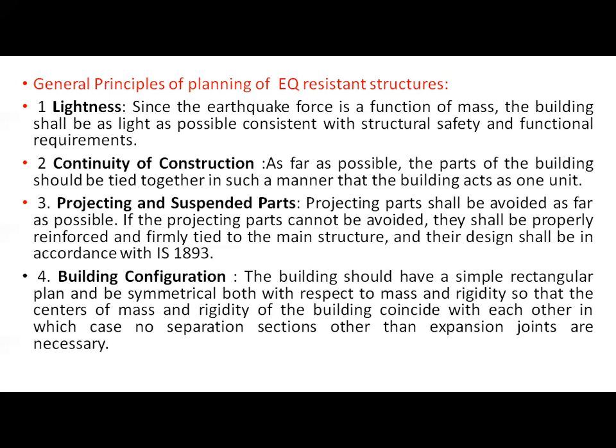Okay, and the center of mass and the rigidity of the building should coincide with each other. In that case there is no separation or expansion. So for that purpose, we should take care of the regularities in the structure in the vertical and the horizontal direction. That all points we have covered in the last lecture also.